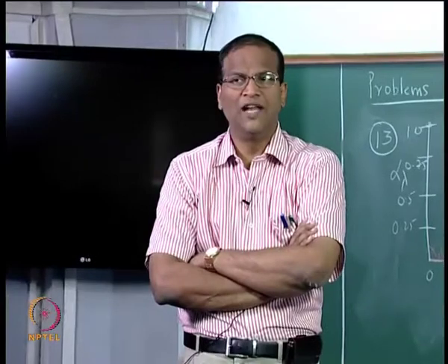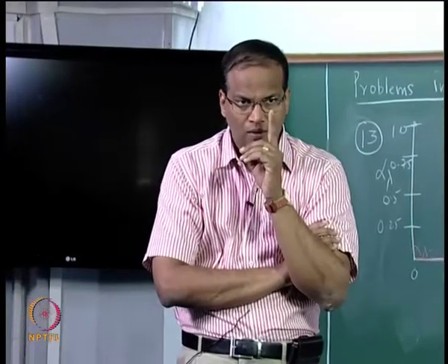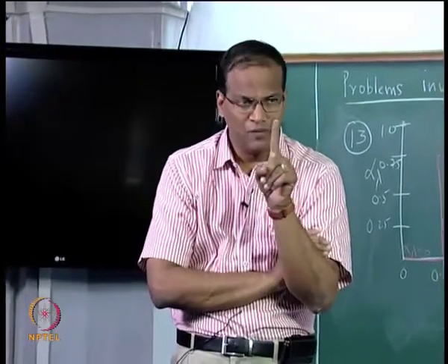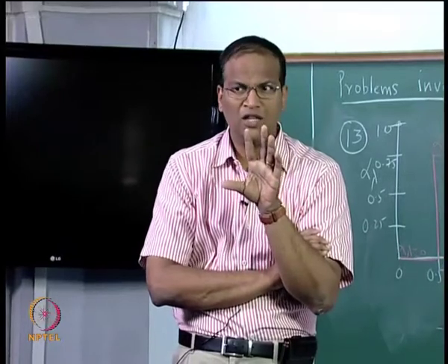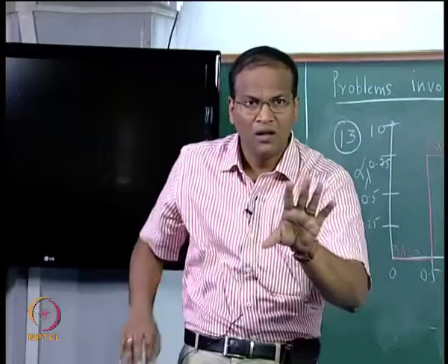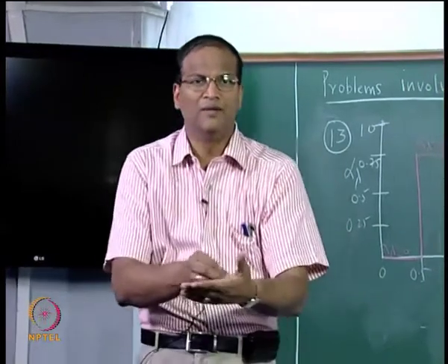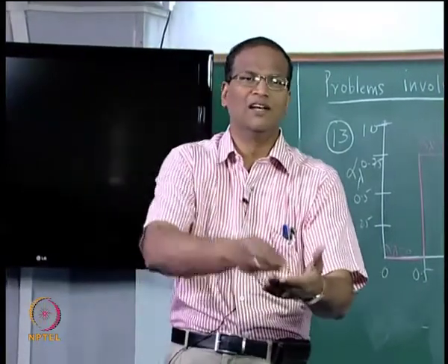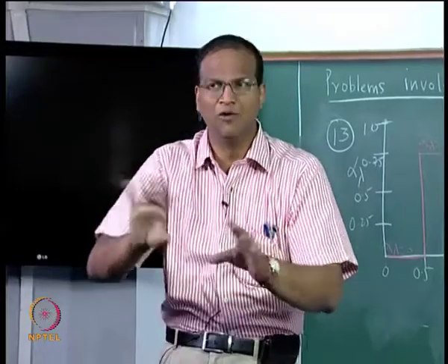Watch very carefully, do not start integrating and wait, this is 1200 watts per meter square, you cannot equally distribute it around lambda. So do not think that it is very simple and straightforward, 1200 integral alpha lambda, it will not work.